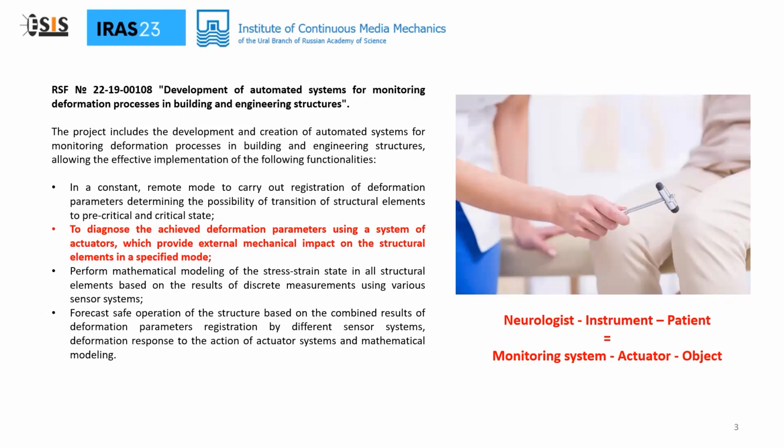One of the significant aspects in the realization of this project is the development and introduction of a method of diagnostics of the achieved deformation parameters using a system of actuators, which provide a specified external mechanical effect on the structural elements. During operation, the structure accumulates defects that introduce significant changes in the performance and can be diagnosed by means of vibration analysis of the evolution of the dynamic response. This is what actuators in the monitoring system are for.